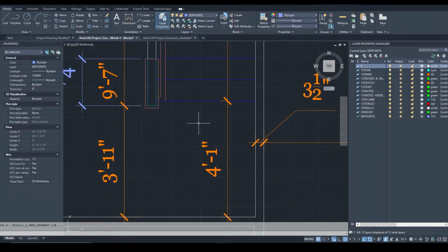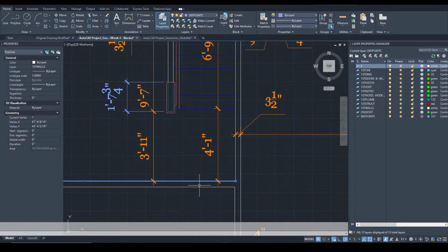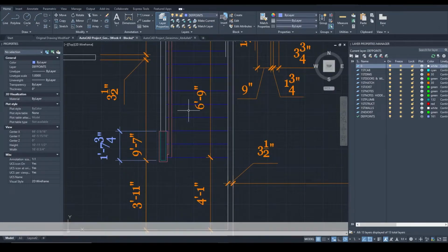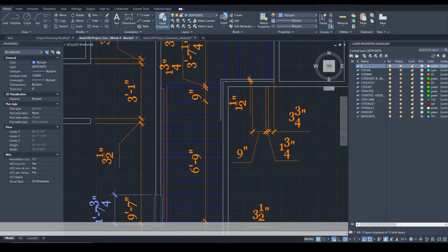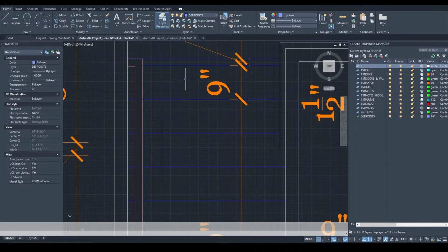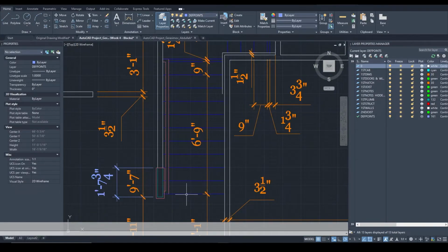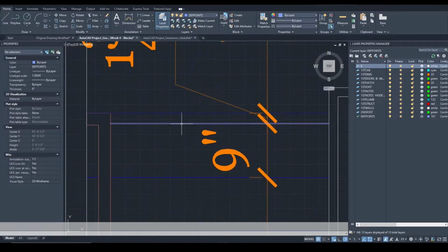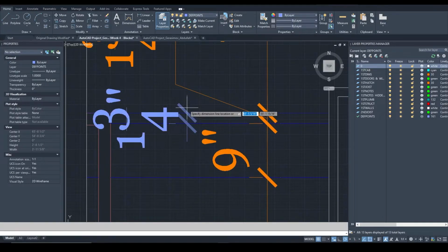These ones are going to start 4 foot 1 inch from this portion of the exterior wall, with 9-inch treads all the way through up until you hit this point. And you can count how many of them I have: 1, 2, 3, 4, 5, 6, 7, 8, 9, 10. After the 10th, you offset your tread line by 1.75 inches, which is going to represent something else. For now, it's too much detail to get into.